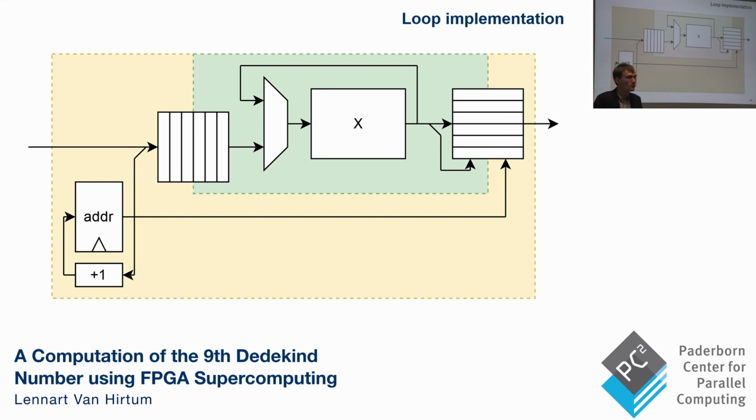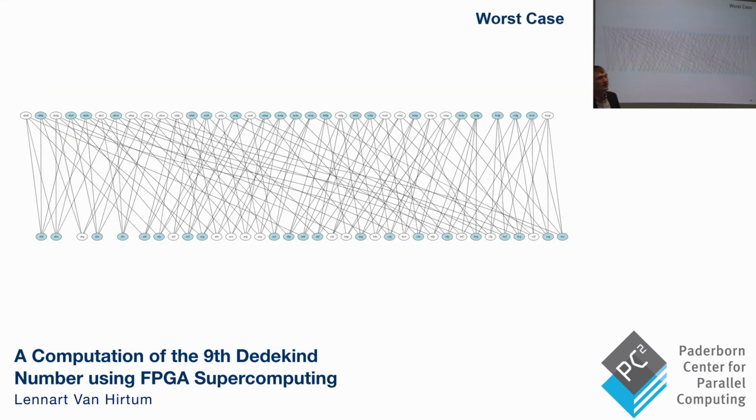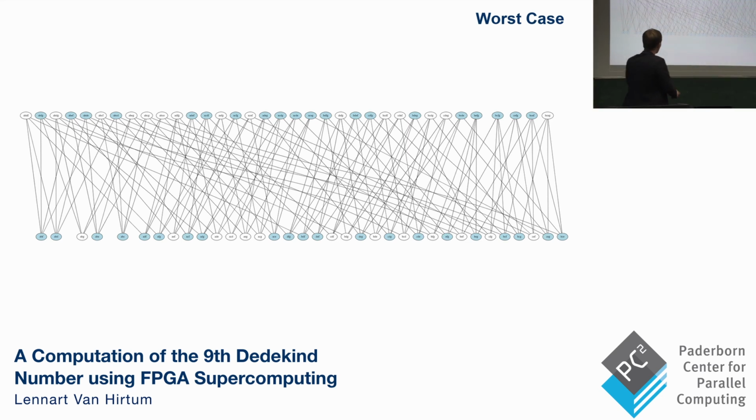So we have to prove that if an element comes in here into the FIFO, it takes a fixed or a limited number of clock cycles before it actually gets written out, so that we're always on time and so that we never read stale data out of the output block. And so I had to find the worst case, which MBF, which graph structure here would take the longest time in this pipeline, and it's actually this one.